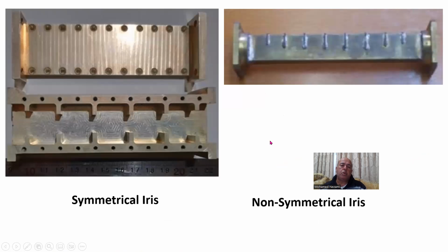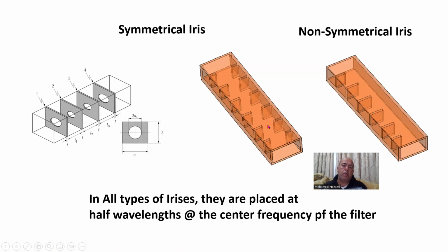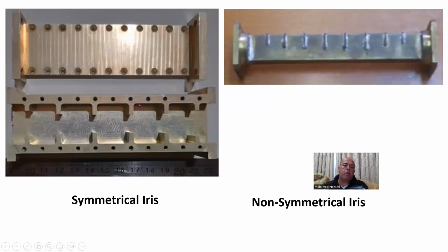We could design it this way, and then do fillets to round these 90 degree corners, and we verify the performance so that we don't lose anything. Usually up to K-band, you don't see any issues with this. I will show you today one of these examples where we take one design, and after we verify it, we fillet the corners so that it is very similar to this here. And we will see that the performance is not changed a lot.